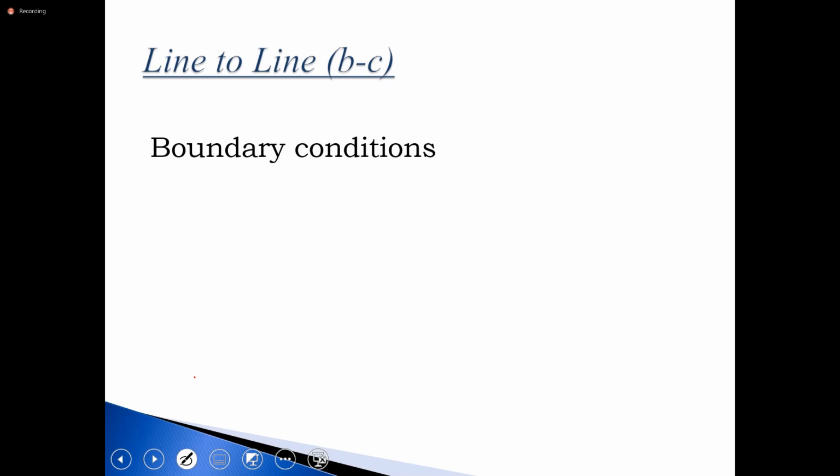No, sir, they're going negative. So the boundary condition is IB is equal to minus IC. Absolutely, because you can only have one current. The current coming out of B must be the current going into C because the two are now connected. That's where the fault occurs. So the boundary conditions are that IB is equal to minus IC and VB is equal to VC.